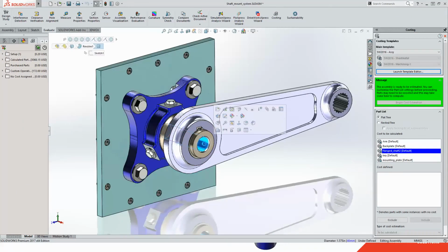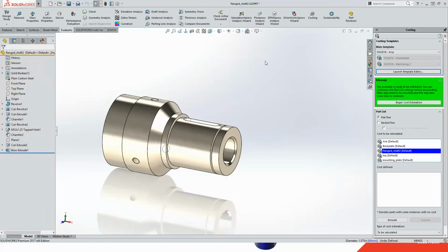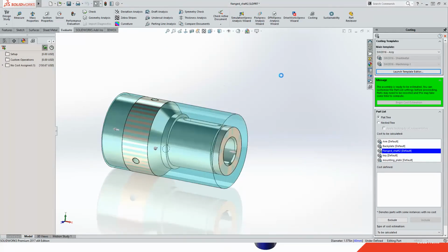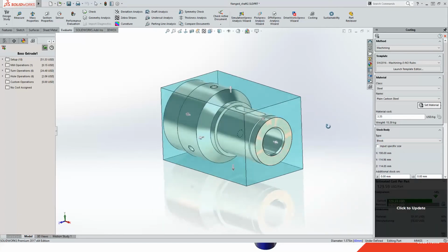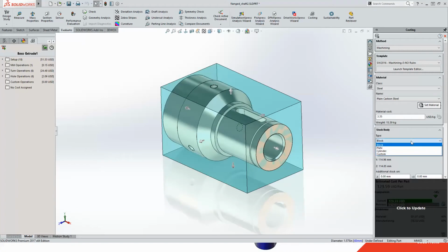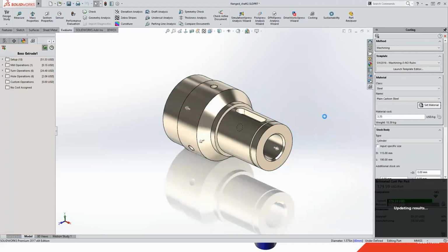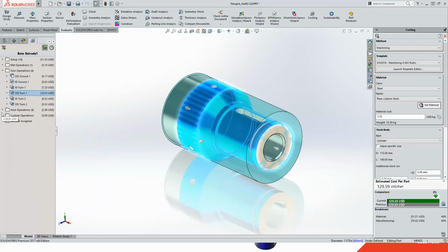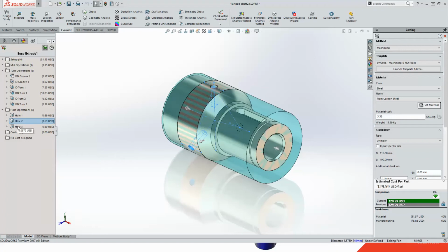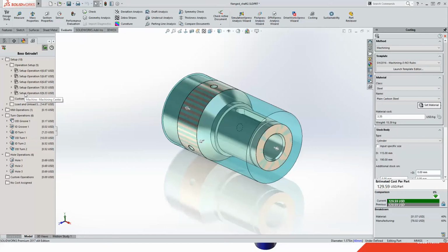Turned parts are a little bit of a different story. Not much, they just have a different operation associated with those. Now with turned parts, what we do is we change it from block or plate to really simply cylindrical stock. Now I could go ahead and change this and make this part as a milled part, but I guarantee you that's not going to be the most efficient way to do this. So as a part that starts with cylindrical geometries, we end up with a component now that's going to be created through a series of turning operations. So what we have here is OD and ID grooving operations, and as you select those, you'll be able to visualize those on screen. What we also see are a series of hole operations, and those come from different setups. This part having 10 different setups, 5 of those being operational or positional setups.